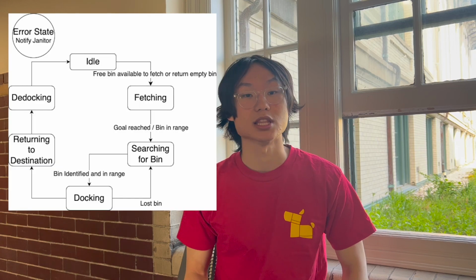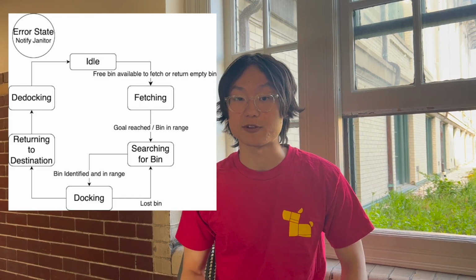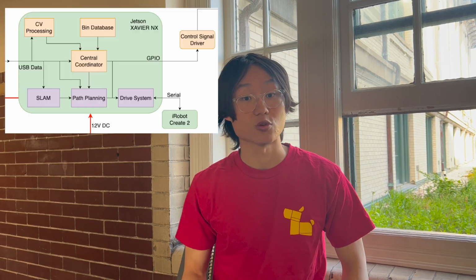The state coordinator is our central decision maker, keeping the robot on track to complete its necessary tasks. It's implemented as a ROS node in Python and uses a state machine to track metadata and implements the logic required for navigating and picking up bins. The coordinator is responsible for interfacing with our database, which stores bin locations. The coordinator also keeps track of the current bin that the robot is navigating to. To interface with ROS, the state coordinator uses the ROS-Pi framework. This allows it to receive the robot's position and LiDAR scans, as well as send movement directives to the Roomba.